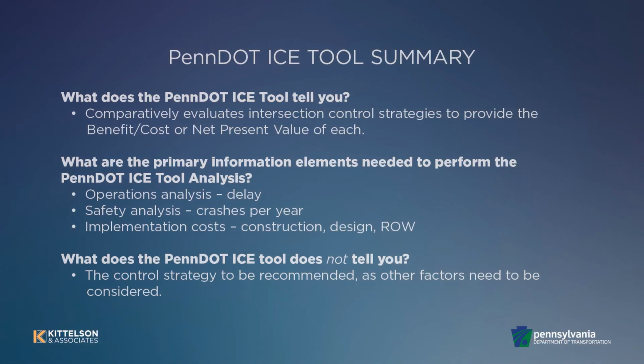Having seen CapX and the PennDOT ICE tool, it's important to understand what these tools do and do not tell you. CapX simply provides feasibility from a traffic operations perspective. The PennDOT ICE tool provides the benefit, cost, and the net present value of each control strategy. The PennDOT ICE tool does not tell you what control strategy is recommended and should be built.